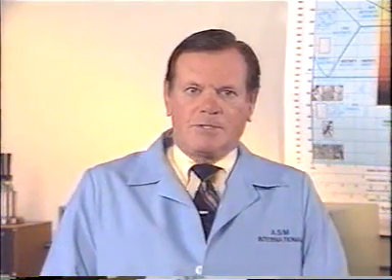Each striation is the result of a single cycle of stress, but every stress cycle does not necessarily produce a striation. The spacing between striations depends strongly on the level of applied loading. The clarity of the striations depends on the ductility of the material. Striations are only visible in relatively ductile materials. Patches of fatigue striations in high-strength steel are less visible than in a wrought aluminum alloy or in low-strength steel.